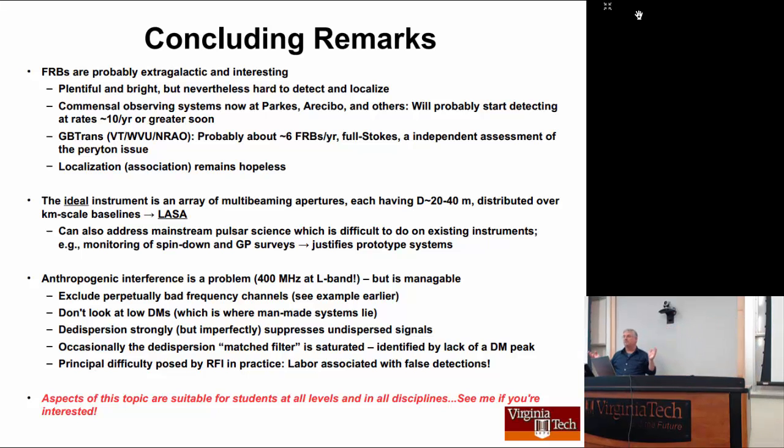We're looking at hundreds of megahertz of bandwidth at L-band, which is about where radars start to peter out, about 1,300 megahertz or so, but all the way through GPS, Iridium, Inmarsat, all the favorite acronyms are in there. We contend with all of those, and we do that by a whole bunch of ways. One is we identify bad frequencies, which are just continuously useless. Fortunately, that's a relatively small fraction. We edit out 5% of the frequencies or so. We're golden most of the time.